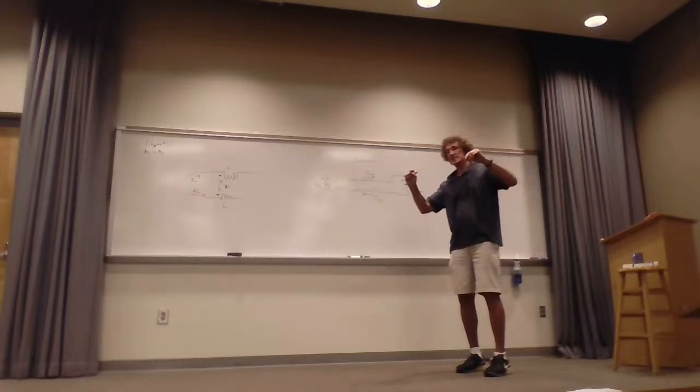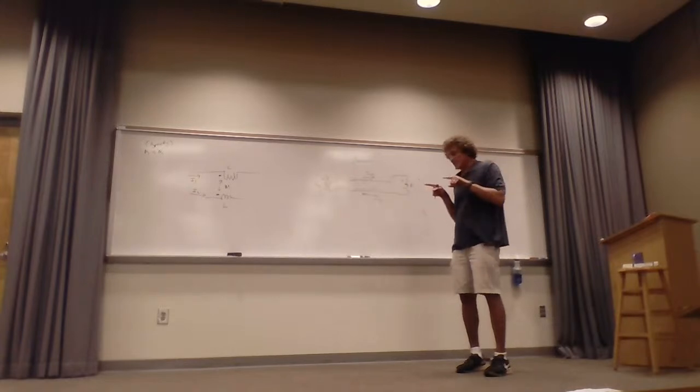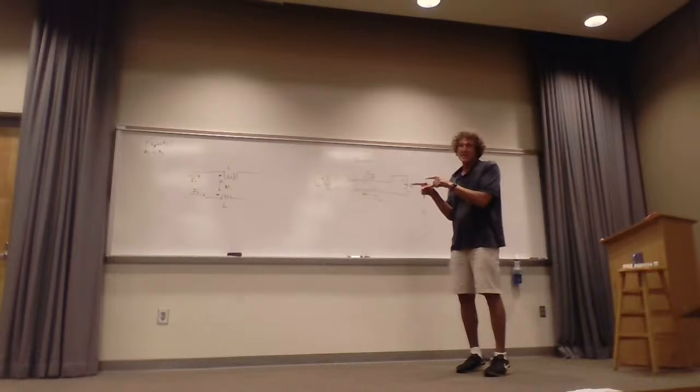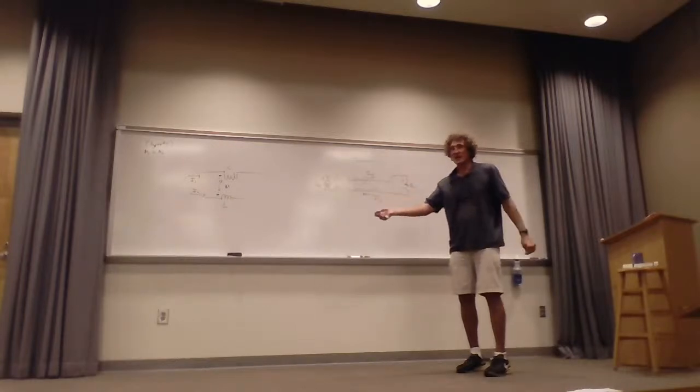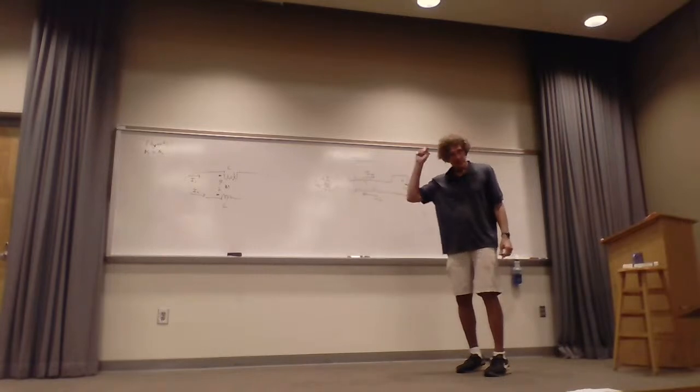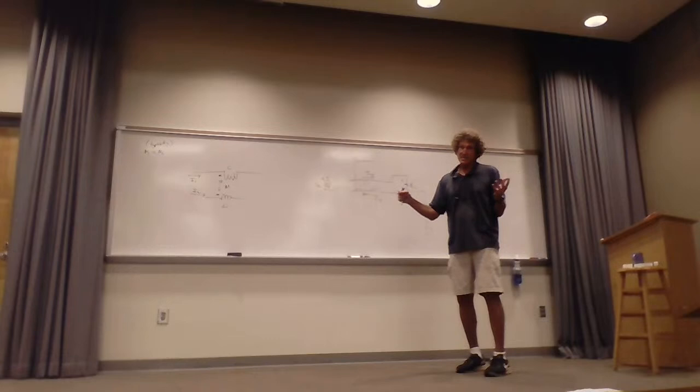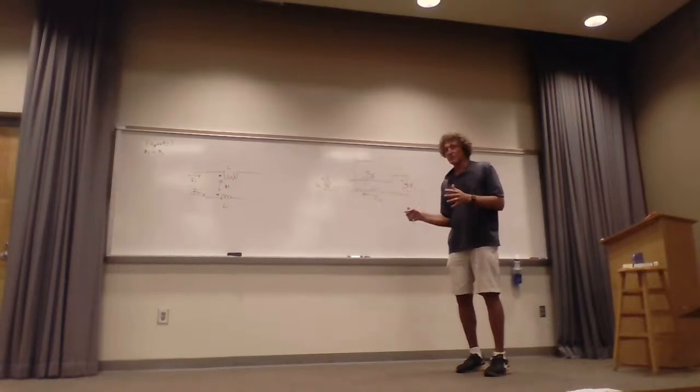When lightning hits, it comes down going the same direction on basically all the connections. It gets there and wants to get to ground. Guess what it does? It destroys the insulation of the transformer. It goes right through the circuit board if it's there, and then goes to ground, and it utterly wrecks the system. Y'all follow me on that? So if you can stop that, it's good. Common mode currents are horrendous.